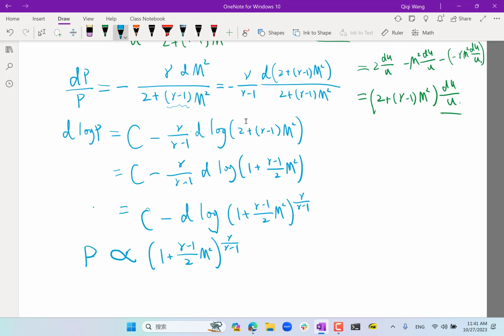And the pressure, as long as the process is isentropic, with no heat addition or subtraction, which is underlying the assumptions we had in the equations above, is always going to be proportional to this guy. What that means is that if you take a fluid of arbitrary Mach number and decelerate it to Mach 0, the pressure is going to increase by exactly this factor.